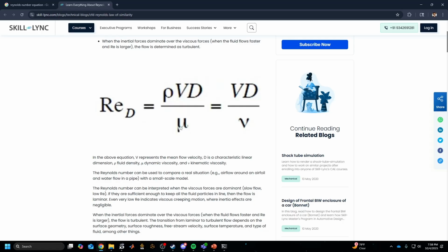So mu is our dynamic viscosity, rho is our air density, v is our velocity, and then d in this case, which I would write as L, is our characteristic length, right? So characteristic length, 14 inches. Dodo was chosen to cruise at 19 meters per second, so that would be our v. Yes, I am mixing units. Yes, it is terrible. Yes, that is how I operate.